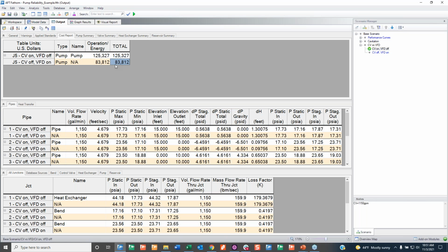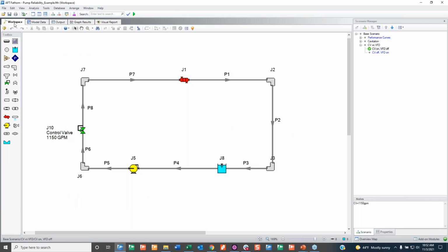How much money are you saving over time by accounting for the time value of money, the hurdle rate, inflation rate, all of that. Fathom's pretty sophisticated. And then you can come up with a final answer of you're saving money. Maybe not useful for an absolute number, because obviously you've got specialists who deal with economics in your company, but it's good for relative comparison. So you can see, well, I'm saving money. That's what I care about ultimately, is that I'm saving money. So when we ask the question control valve or VFD, fight, who wins? The VFD wins.